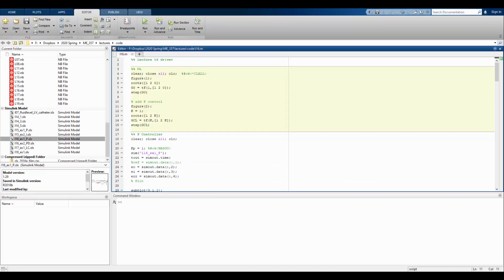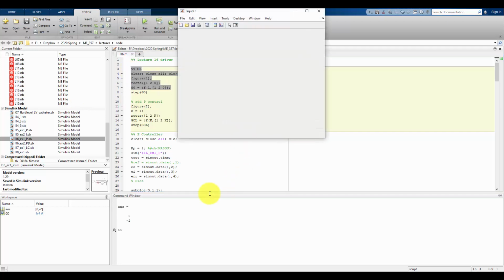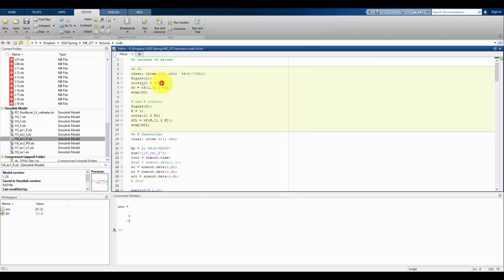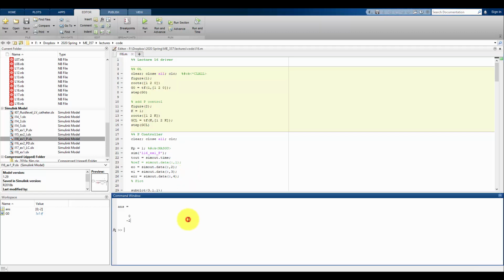First, I actually want to go back to the open loop system and see what it's going to look like if we didn't have a controller. So first, let's find the roots of our system. Like I said before, 0 and -2. That 0 indicates that we do not have a stable system. The two poles in this are not both located in the left half plane. And I can make the transfer function 1 over s squared plus 2s.